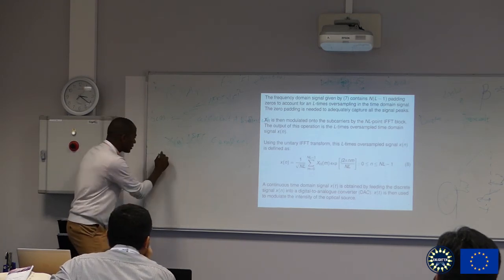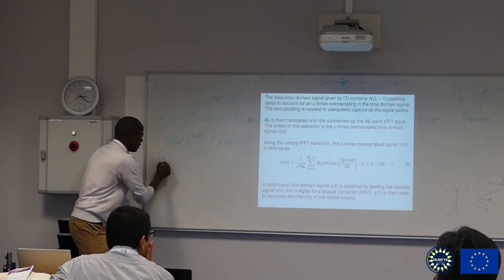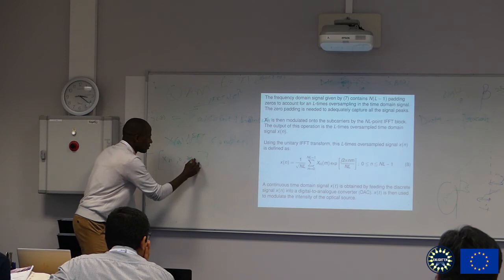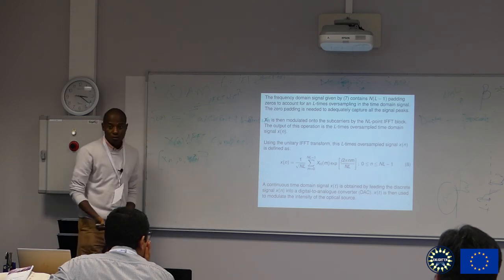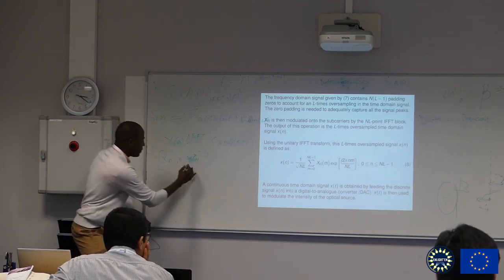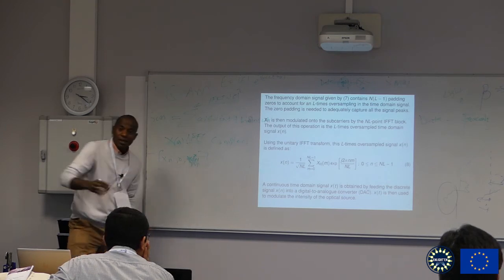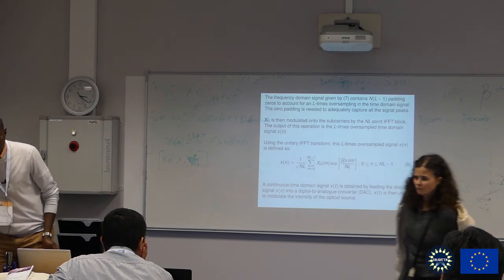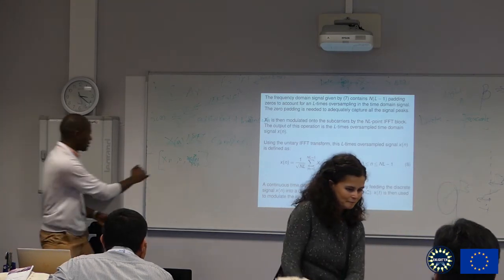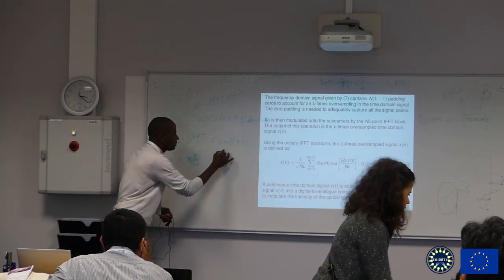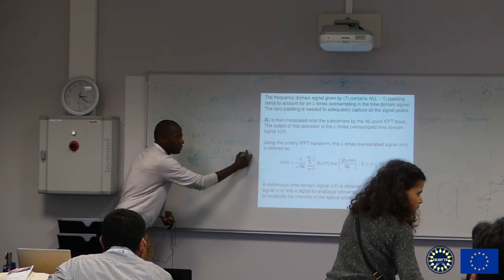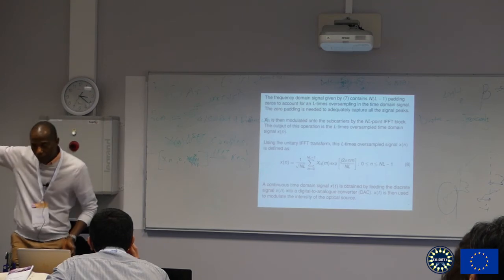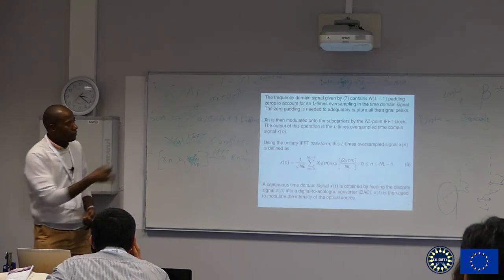So what you can do is replicate it: X_n, you put 0, and then you put the complex conjugate. And then you flip it. That is a symmetric property of IFFT itself that we can use. So if you do this, and then you carry out IFFT, the output becomes real. That's all. But it's still going to be bipolar at that point. And then we add our DC.